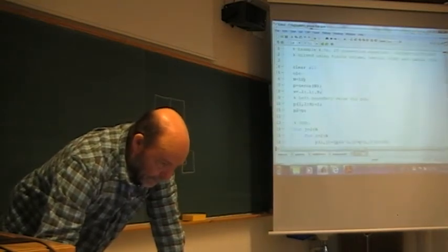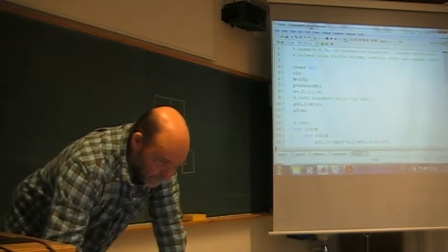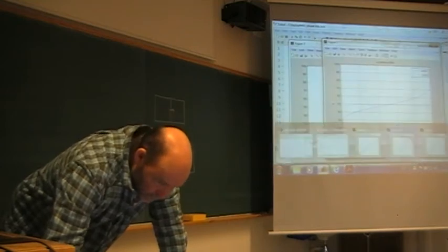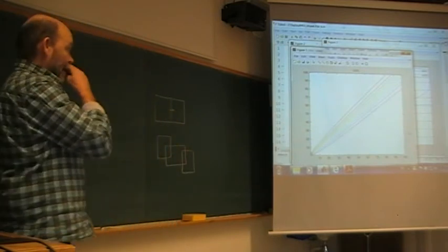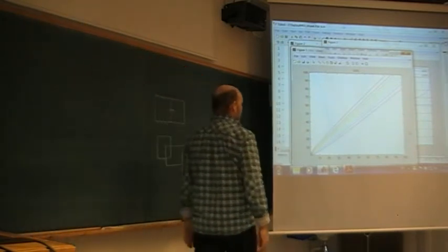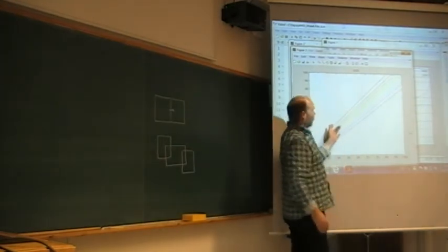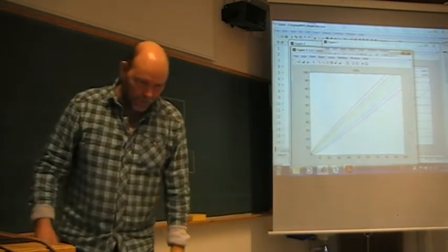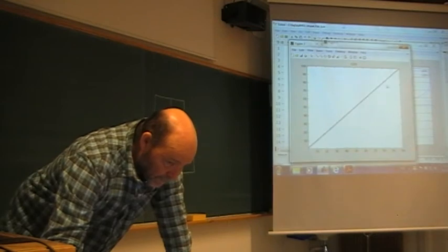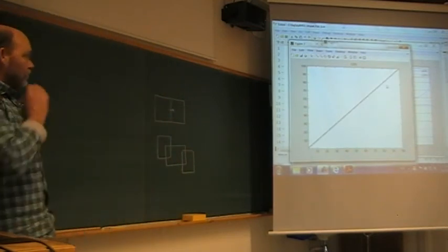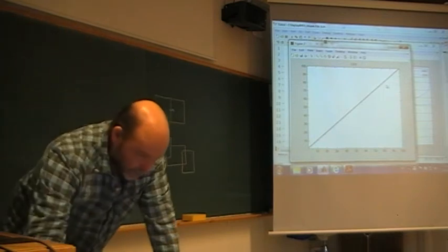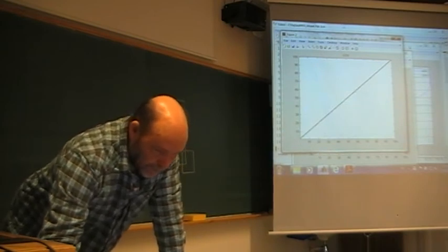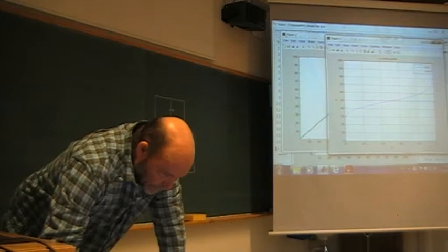Here it was a 10 by 10 case, so if you jump to a 100 by 100 case, where's figure 1? Here. You get the same image, it doesn't help. You still have this smearing out effect from the first order upwind scheme, no matter what you do. This can't really be avoided. But here, it was then possible to achieve the correct solution with the central difference scheme. Although it shouldn't be, because it should then be unconditionally unstable if you sort of program it directly. But let's have a look.